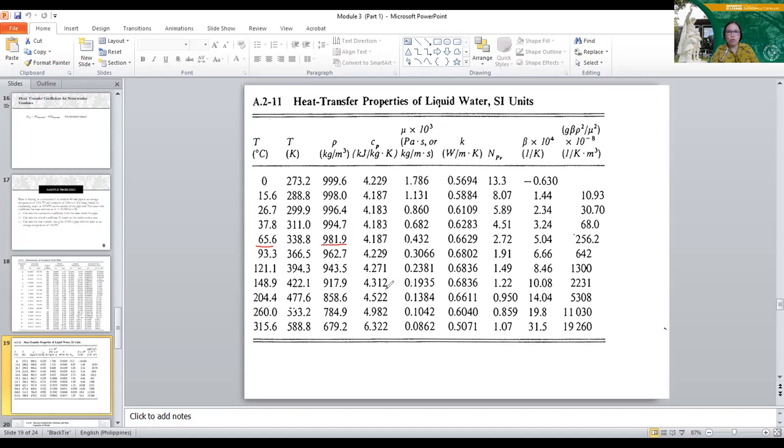We also need the viscosity there in the Reynolds number. We need later on the Prandtl number, and we also need the thermal conductivity of the fluid itself. This thermal conductivity will be the one appearing in the hD over k formula later on, that is in the Nusselt number, where we will determine the heat transfer coefficient.